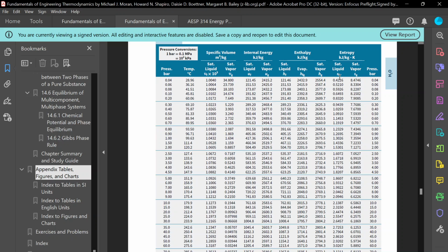Is this a little more clear now? We have it on the table, right? Temperature hasn't changed. Your saturation temperature and pressure haven't changed, so you have already read it from the table. How do you write the vapor quality? Okay, so you read the entropies, and the process between station 1 and station 2 is isentropic, right?